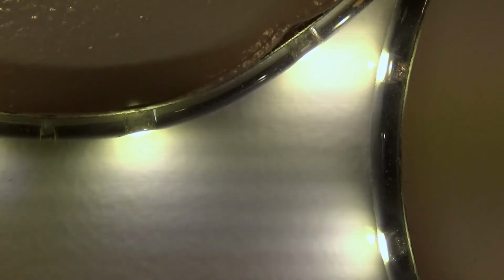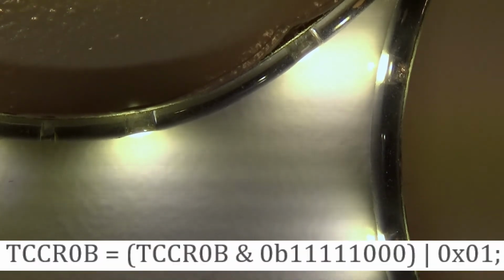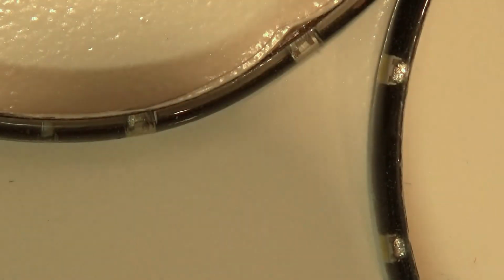As mentioned earlier, the PWM function of the Arduino is designed for this work. The clock is at a frequency of 500 Hz. By default, the PWM function quickly turns on and off the load that it supplies. A higher frequency reduces the perceptible flicker. It is possible to increase the frequency with a simple command line up to 62.5 kHz. It means 125 times faster than the base frequency. The flicker, then captured by the camera, instantly disappears.